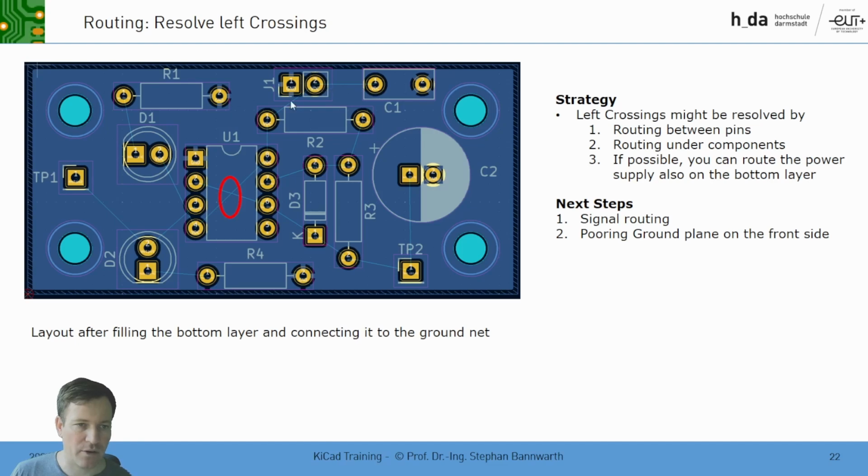So connecting on the front copper all our flywires with traces so that the flywires are gone. And then we pour our ground plane on the front side with copper. As I said, if you only have traces for these fly lines here, there's a huge amount of copper which has to be etched away. And this means your etching liquid is saturating early, producing costs. That's why you avoid it. And you pour copper and only slice the copper where you have the traces.